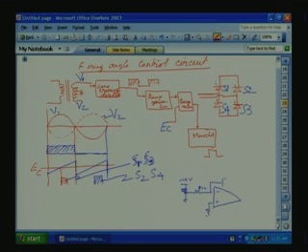You can choose your capacitor so that the RC time constant can be adjusted, so that this capacitor will slowly charge. Then at this zero crossing point, we should discharge it. For that purpose, these zero crossing points you have to detect again through a monoshot, giving a small pulse at these points. At this pulse, the capacitor should discharge quickly.